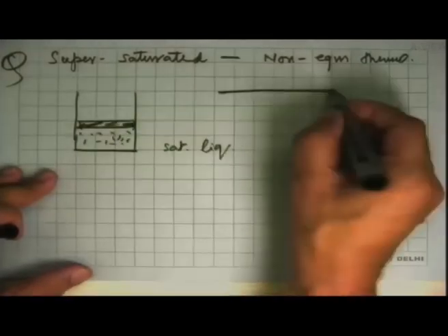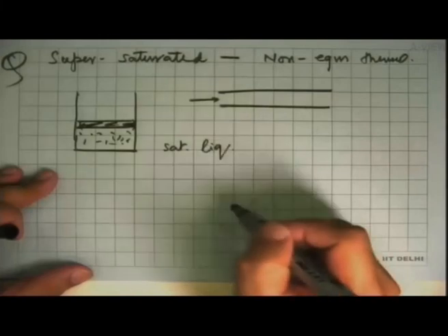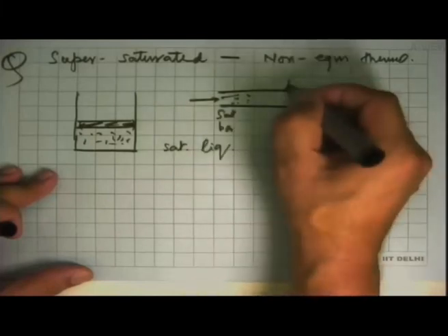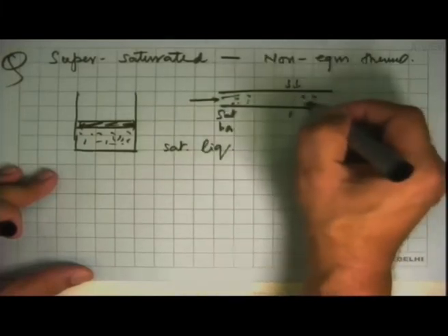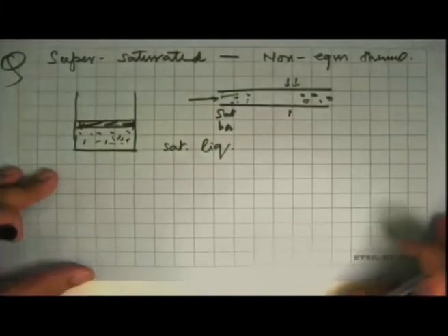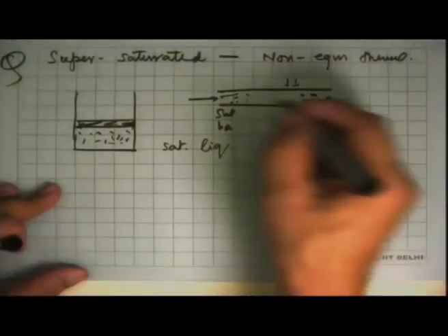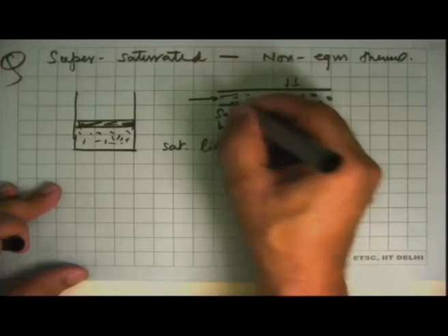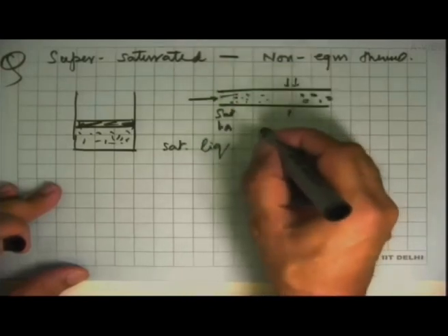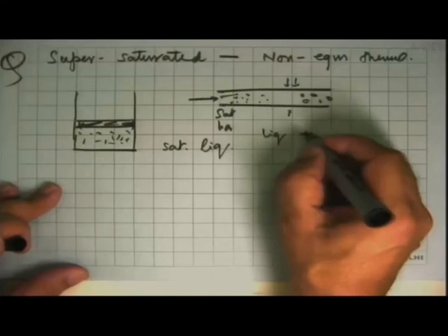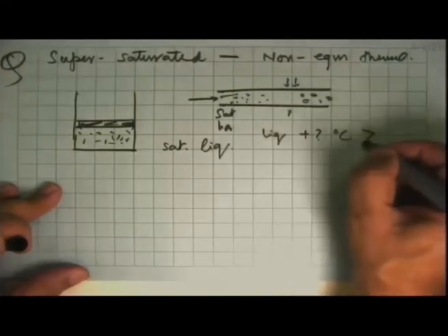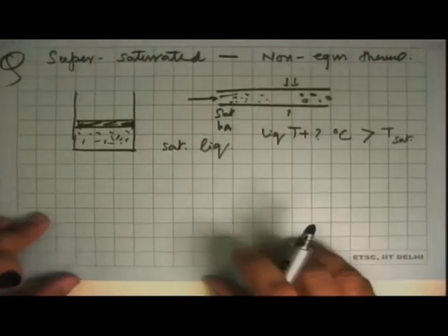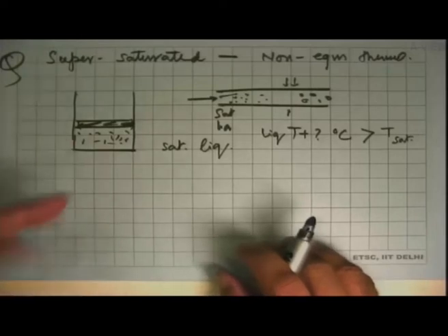This or its counterpart in a flow, that you are pumping in saturated liquid and you are heating it now, and you expect that vapor bubbles will be formed. What has practically been observed is that instead of exactly happening at the saturation temperature, the liquid remains in the liquid state for a few degrees greater than the saturation temperature, and then it changes phase.